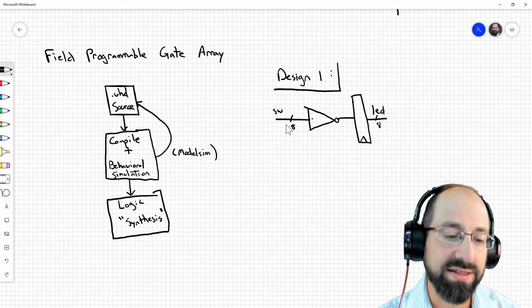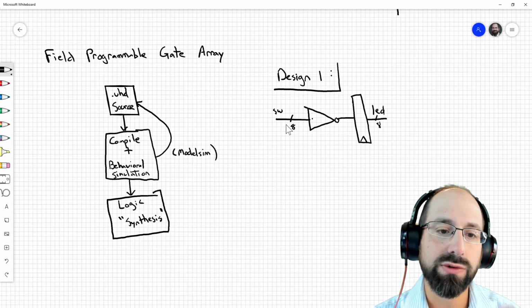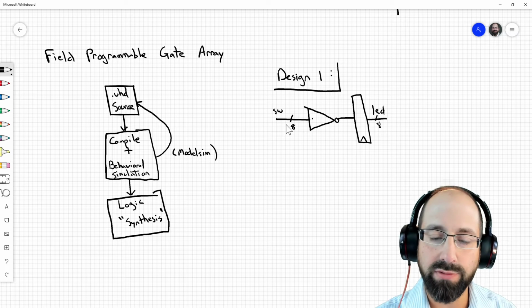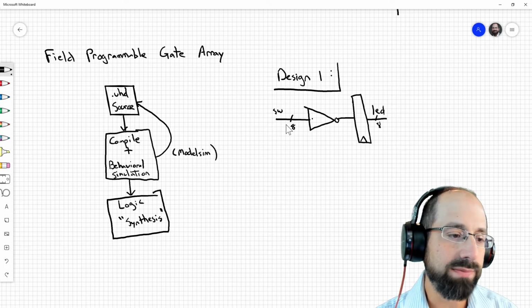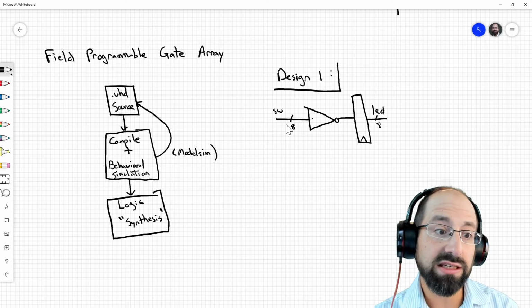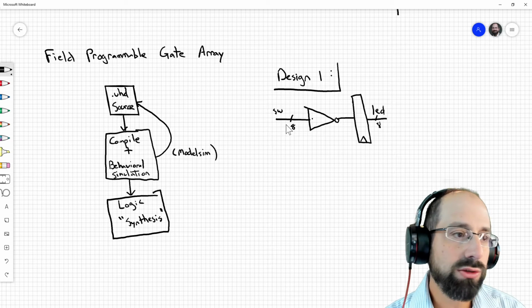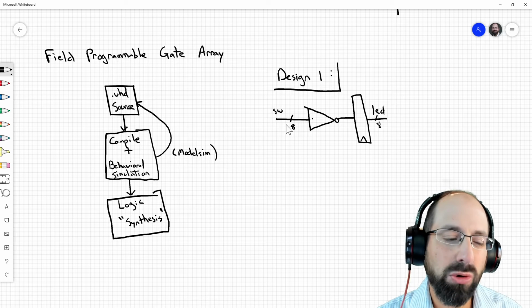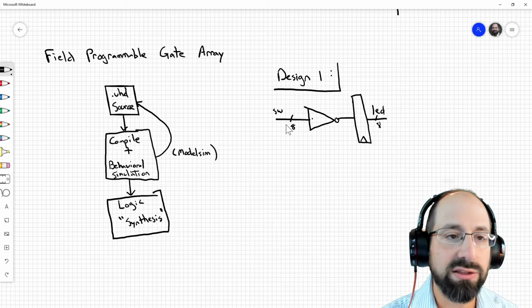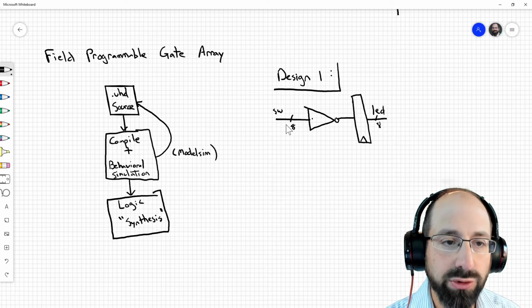And the idea of this synthesis just means to combine things. It's taking that model of what your hardware is supposed to be, and it's attempting to map it to what library of computing gates and other things are available on your target device. So synthesis would vary widely depending on which type of FPGA you're using. Also, if you're mapping to an ASIC, or any other sort of hardware target, the output of that synthesis would look quite a bit different. It's going to give you something a little bit closer to a gate level view of what's happening in your design.